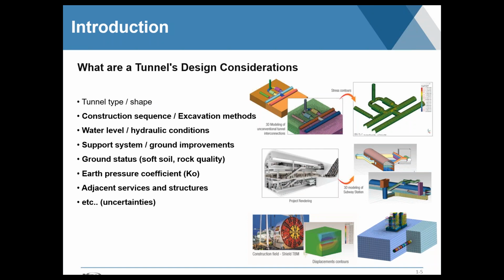However, as geotechs, we know that there's a lot more to consider going into a tunnel, and that's where we'll be seeing these other key points in the process. But everything from the sequence of construction, which comes down to the excavation method, has to be determined by the geotech engineer, and other local conditions, for example, what would be the water level or the pore pressure to be considered, if that needs to be improved, basically draining, what kind of status we have for our ground.